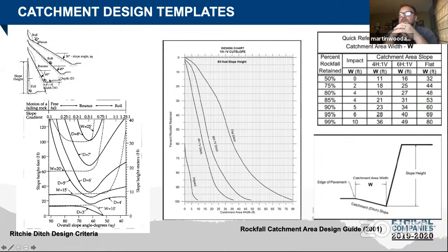And so around 2000, 2001, Larry Pearson with the Oregon DOT did some more research, and they actually did this with the Colorado Rockfall Simulation as well. They came up with a single angled slope for the catchment area, which is actually what's constructed out there. And so you can do the same thing with these kind of areas. You can say, well, this is for a 1-to-1 slope of a slope that's 80 foot tall. Your catchment area is 20 feet high. You can take a look at where the rock will fall, where it will get to, and where you have to do anything to contain it.